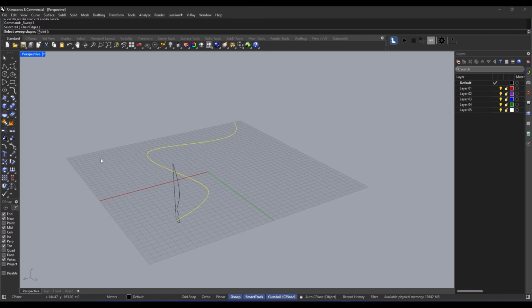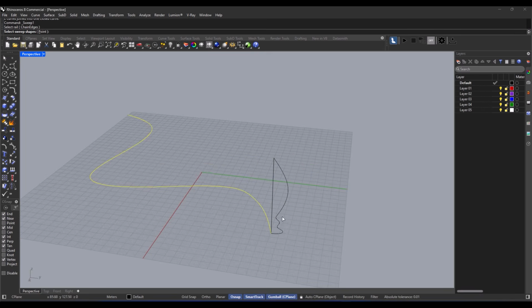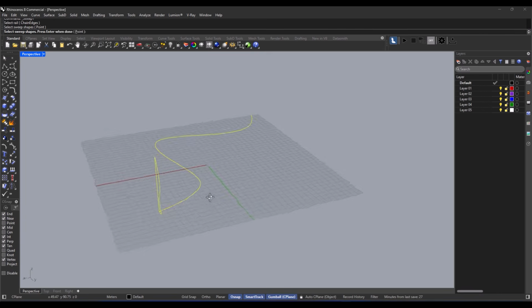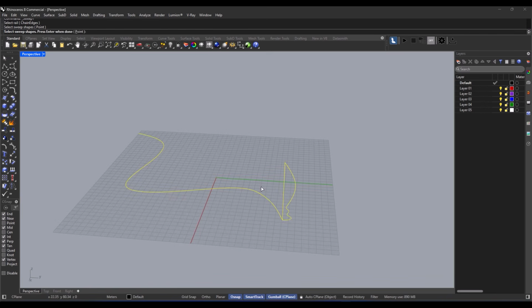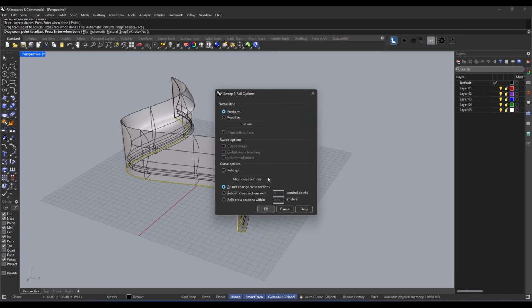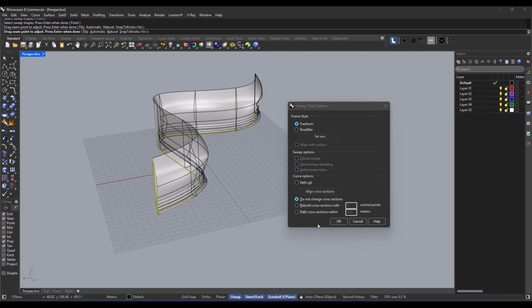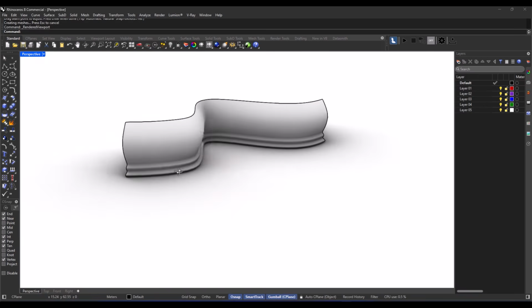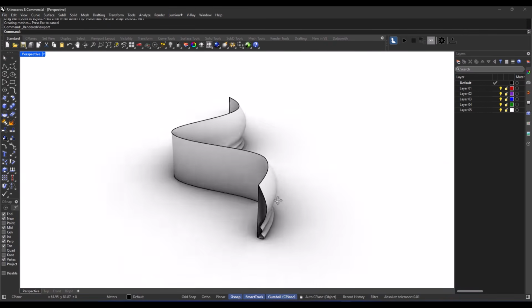Just one. 2. Then you pick the cross-section curves in the exact order that the surface will pass through them. Super important. Oh, and just a heads up, if you're selecting multiple closed cross-section curves, there's an extra step to adjust those curve seams. So keep that in mind.